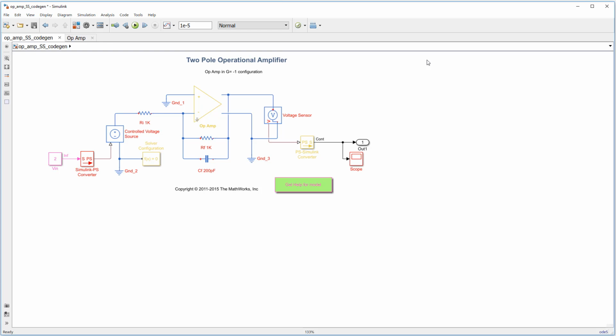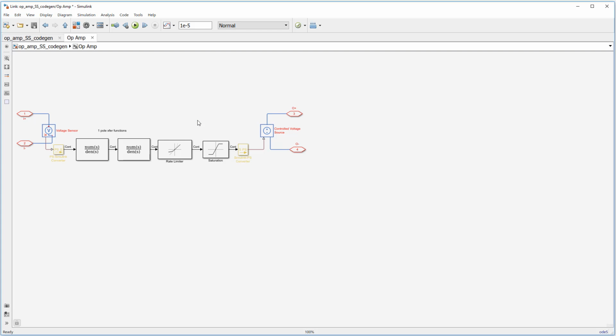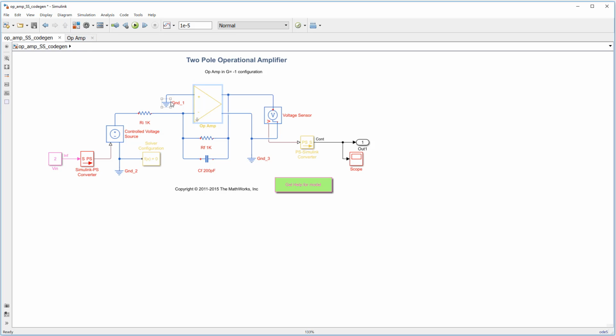In this example, I have a behavioral operational amplifier, which is built using high-level Laplace and mathematical models. Note, however, that I'm using some circuit elements to control the biasing and the loading of the operational amplifier. While Simulink is not a SPICE simulator, it does allow for the inclusion of circuit-like parasitics, including impedance mismatch, reflections, and VSWR. This allows us to create a more accurate behavioral model of the op-amp, and that really is the goal, to create a fast behavioral model.